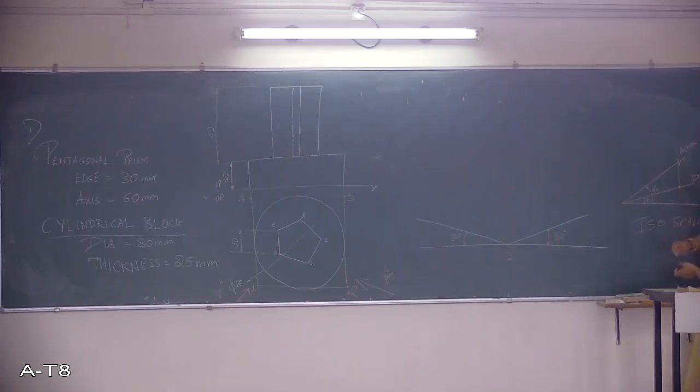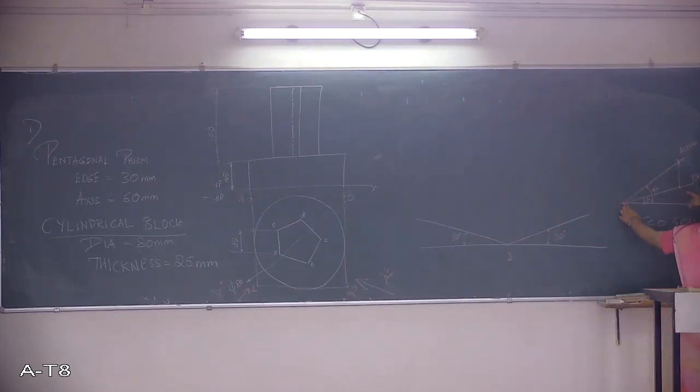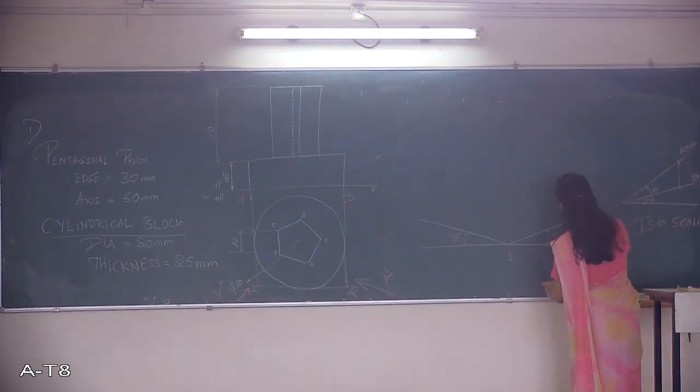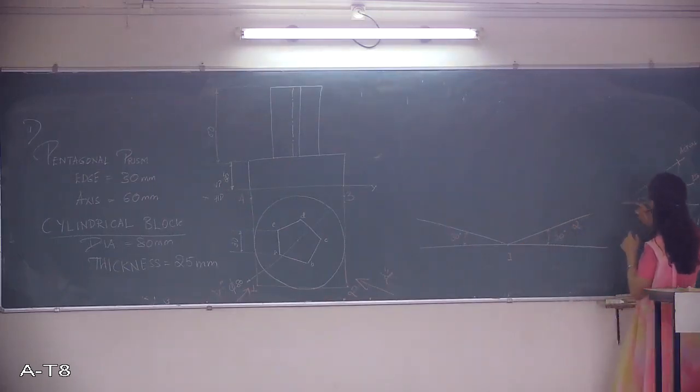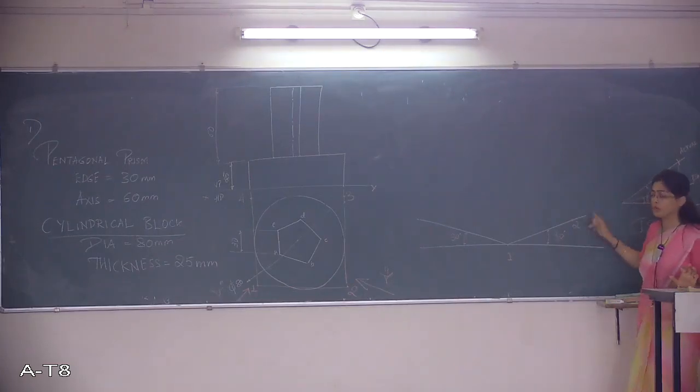Now this is the ISO scale reading that you need to take, which has to be marked on this part. So now, by taking the compass again, you measure this and that should be marked here. So you have measured 2 here, by referring to the iso scale. So you have marked point number 2.